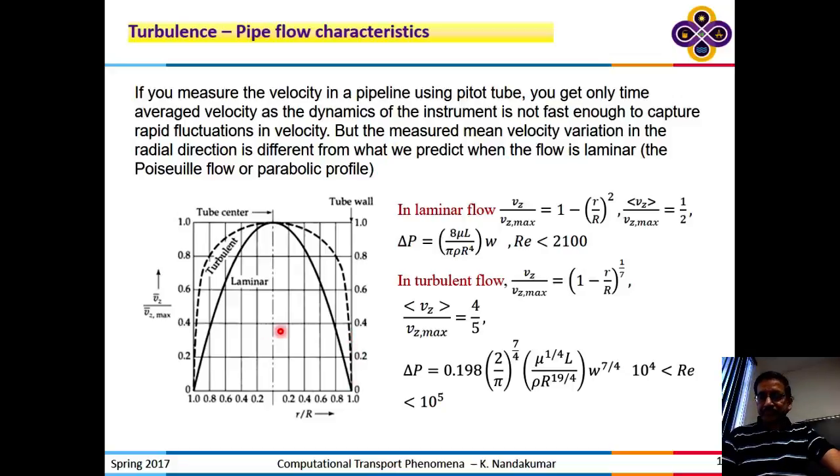Okay. And of course, in laminar flow, you can analytically solve this, get the velocity profile, and get the pressure versus velocity relationship. That's a linear relationship because the Navier-Stokes equation, when you throw this term out, becomes linear, because you have that chart.